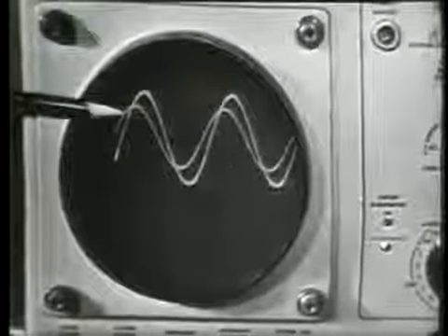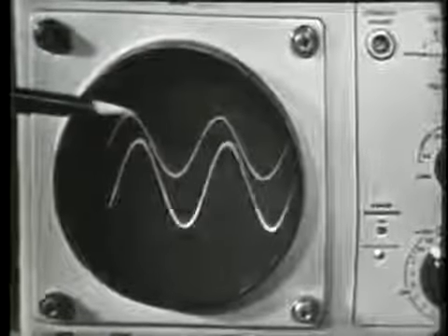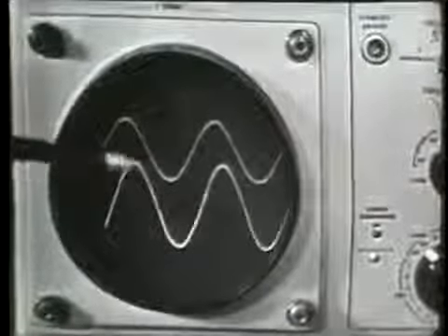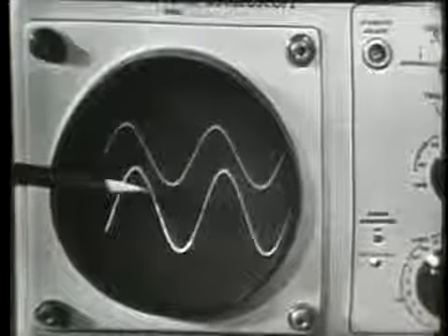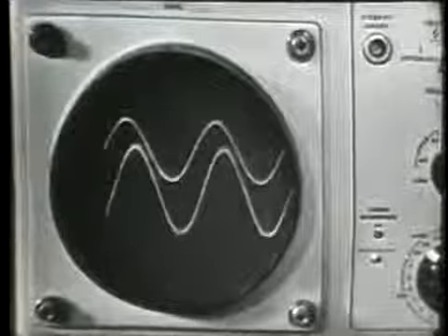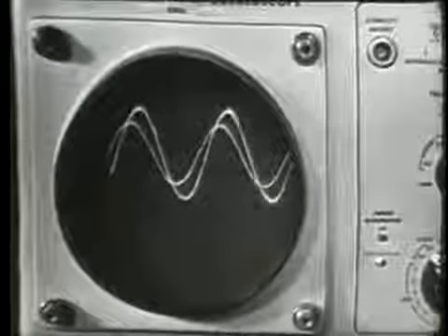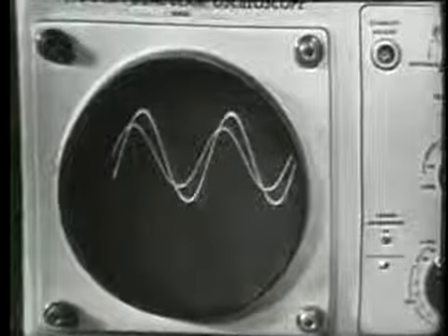But you'll also notice another phase difference. Only this time it is the voltage across the inductor which is reaching its maximum value right here sometime before the voltage applied reaches its maximum value. So this, of course, proves, just as we found in our vectors, that the voltage across the inductor leads the voltage applied, while the voltage across the resistor lags the voltage applied.